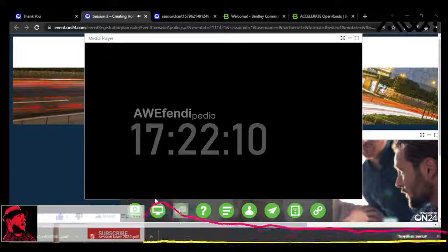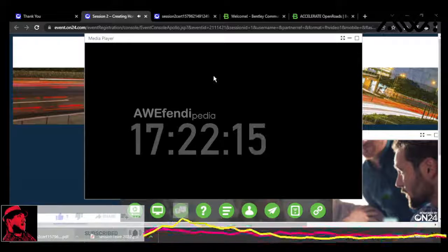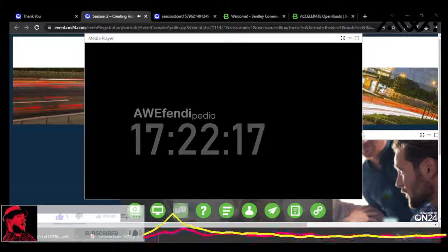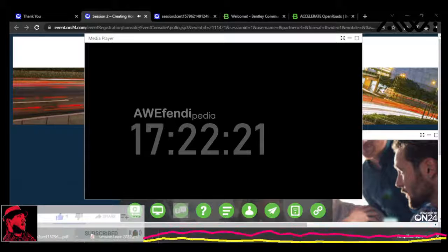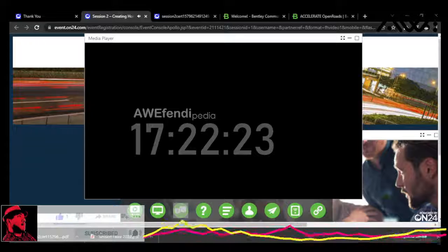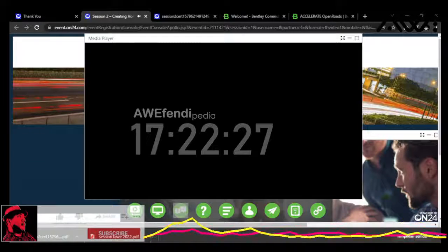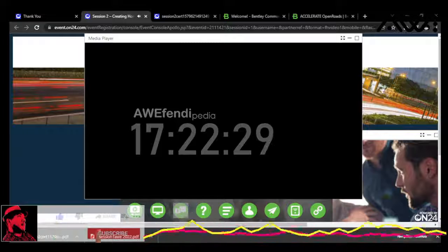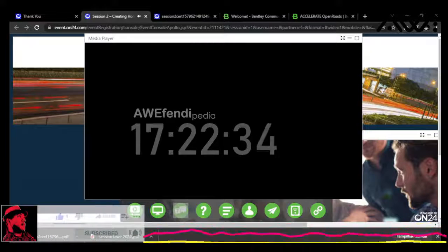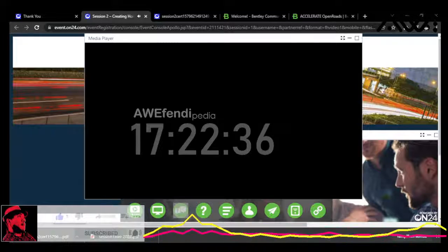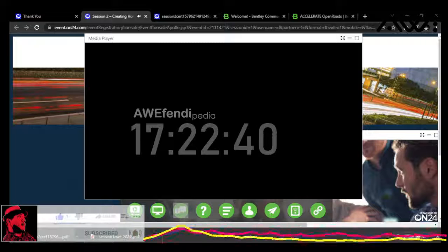So it's south 89:02:28 east. Okay, south 89:02, 28 seconds east. And I click the tab key or the enter key. They both lock, and you'll see that it picks that up as a field. Now to place that element, again, if you're new to OpenRoads Designer and the interaction, to place that element, I need the data point. And that places that element now in the file. So now I have that first tangent element placed.